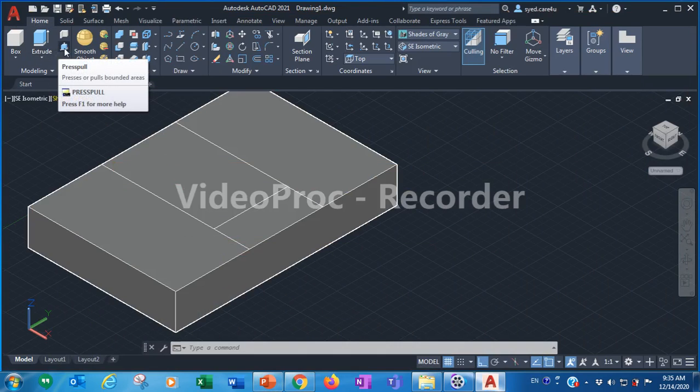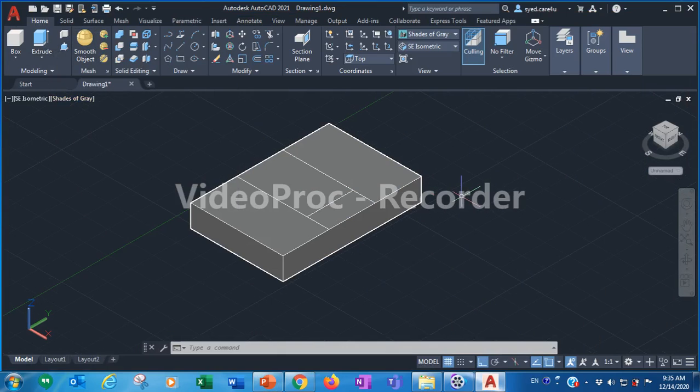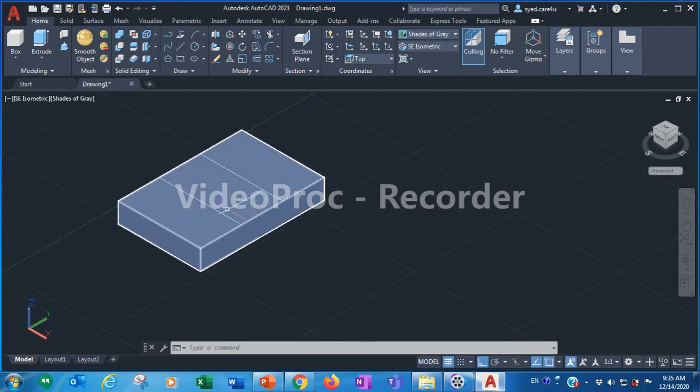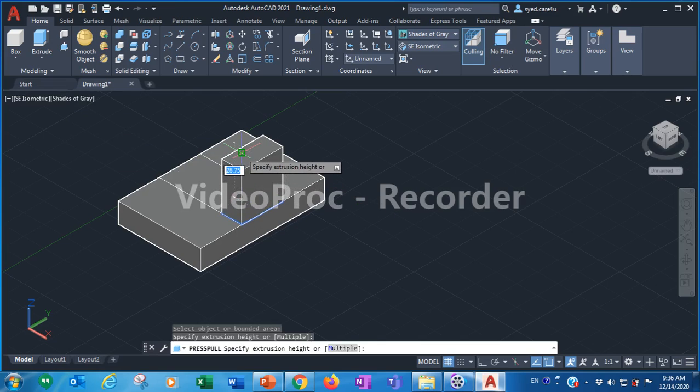Now select the press pull command again. The press pull command has two uses. It can make or it can break. Last time we saw that by constructing this we created a 3D object using the press pull command. This can also be used to break a particular part, to remove a particular part from the existing figure. Now select press pull, come into this rectangle, click here. If you go upside and click, it will construct and this shape will be formed.